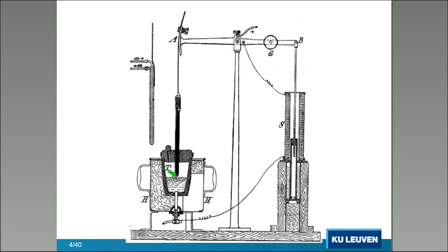So in fact, the arc furnace is a transfer of heat. It's a transfer of heat by radiation. The heat is radiated from the arc to the melting bath. The arc is at a very high temperature, 6,000 degrees Celsius, maybe sometimes 8,000, 9,000 degrees Celsius. So a huge amount of heat, and by radiation, the energy is by heat transfer radiated to the top of the melting bath. I will come back to more in detail to the components of the electric arc furnace.